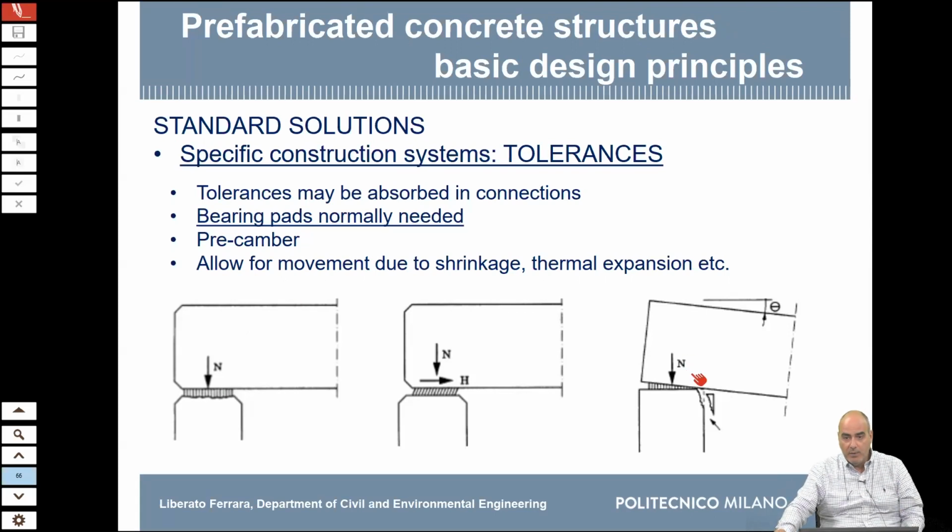So you have to accommodate this rotation and avoid that when it rotates, the beam hits the corner of the column, because at that point the force goes all through that corner and you chip it off. It's not a static problem, it will never happen. But it's something that the owner can call about and you make some repair. It's an aesthetic problem and so on. So these are issues that you have to take into account.